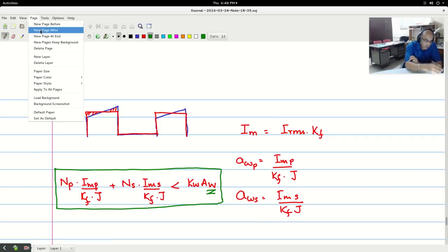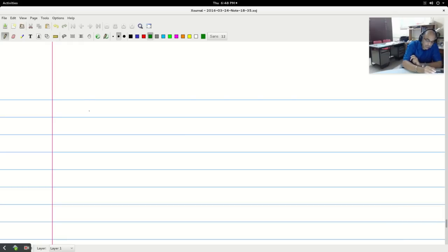that we will use. So if I take the product, one is AC into Aw. Now AC into Aw will give you a product called area product, AP. This is in meter to the power of 4. This area product is a parameter that you can use for choosing the core.